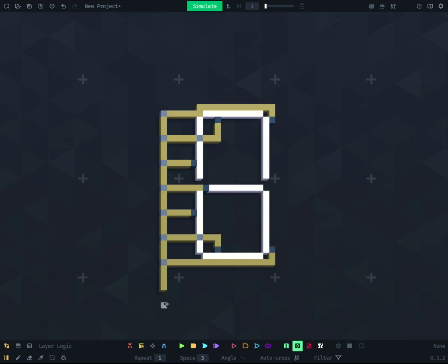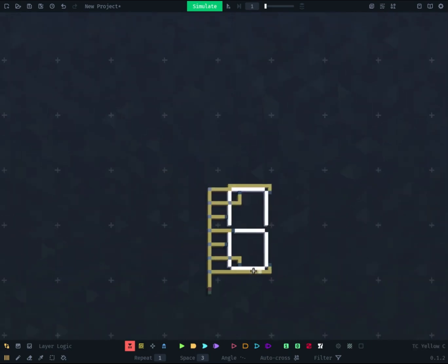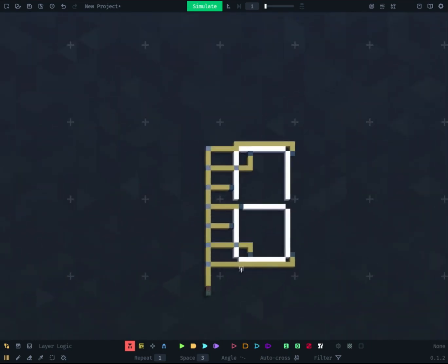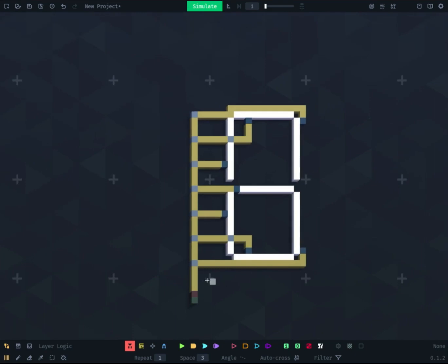And then a latch here with a write, so the output of the latch can be passed down through the wire. And why we want to use the crosses is that if we want to use it for multiple numbers, this wire is gonna pass down through here, and we don't want that wire to be part of that wire, because if this wire is, let's say, lighten up, we do not necessarily want to have all of these wires lighten up.